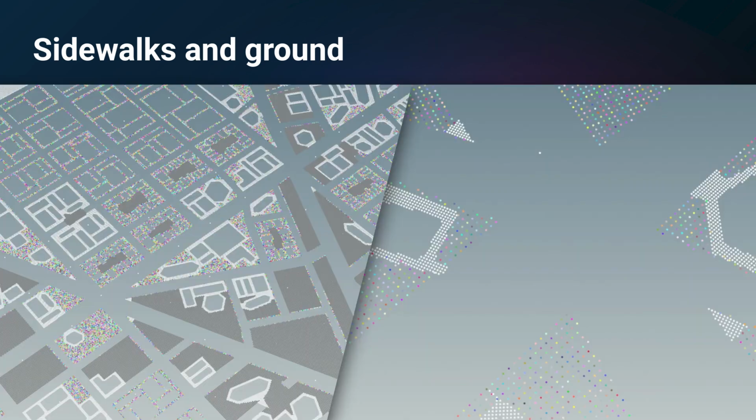For the ground itself, we would subtract the building coverage to save a bit of surface, and then cover it with a point cloud where the density would be adjusted to its ground tile size. If you recall the 500,000 triangles pre-displaced piece shown before, here you can see how many times we would use it over the city ground. 2.5 million times, that is. Yeah, that is 1.25 trillion triangles for the ground itself. We wanted things to look sharp and good.